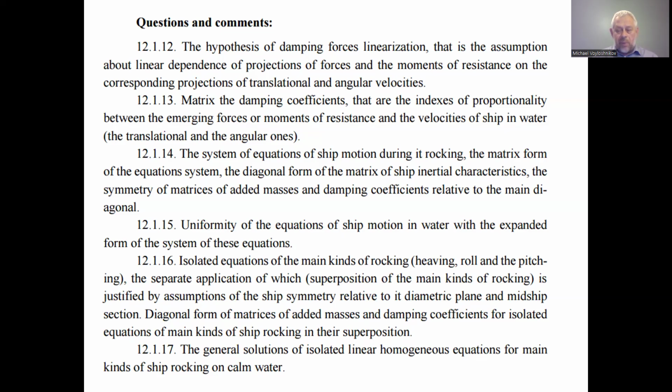The amplitudes and the phases depend on the initial conditions. And the amplitudes reduce gradually due to the damping decrements with the availability of resistance to the rocking of the ship. And we can find the natural frequencies of ship rolling, pitching, and